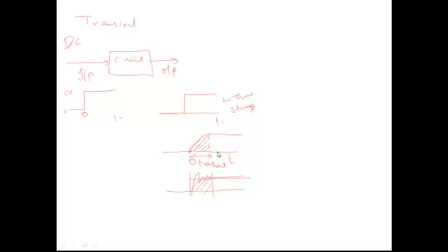The output where it has a constant value is called the steady state. So what you need to understand is, if inductance and capacitance are involved in a circuit with a DC source, then you cannot expect the output to be purely steady state instantaneously.